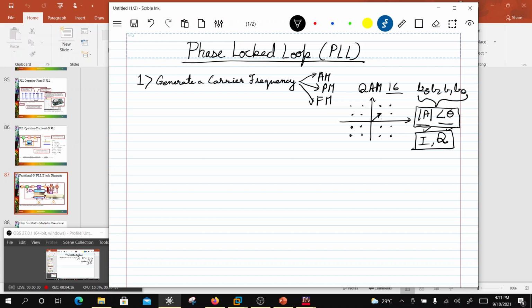And if I change anything with I and Q relative to each other, then this constellation is no longer going to be as you see it. For example, if I was to introduce an amplitude imbalance, then this entire thing is going to rotate, or it's going to skew, or if it is non-linear, then these symbols may move inwards.